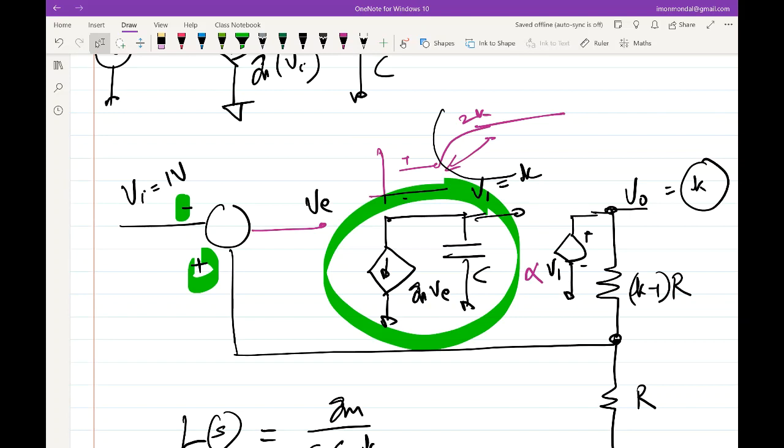We had essentially said that you have this transconductance loading a capacitance that is forming the integrator, but the integrator is not directly seeing the resistor stack, right? So it was being buffered by a voltage controlled voltage source, and the voltage controlled voltage source gives you infinite impedance. So there was no current sharing between the capacitance and the input side of the voltage controlled voltage source.